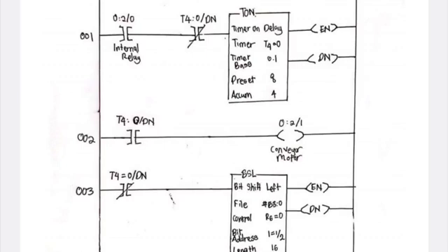The proximity sensor is placed 8 steps from the capping machine to set the bit position to operate the capping machine accordingly. Bit register B3:0 is used. Thus, the capping machine should operate when B3:0/0 is shifted to B3:0/7. So, when the bottles detected by the proximity sensor are more than 7 steps from the capping machine, it will operate based on the bit shift register.